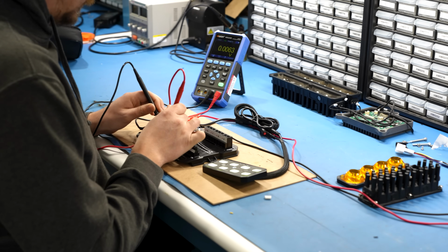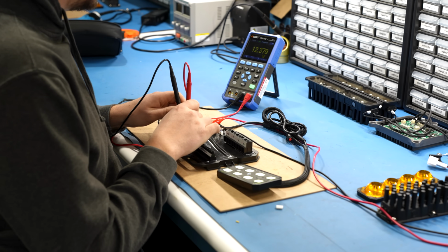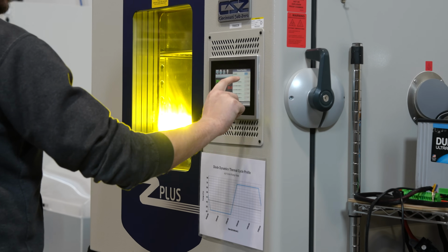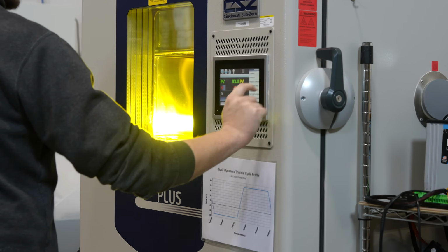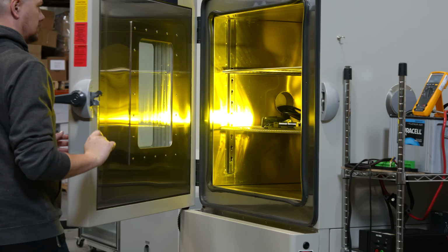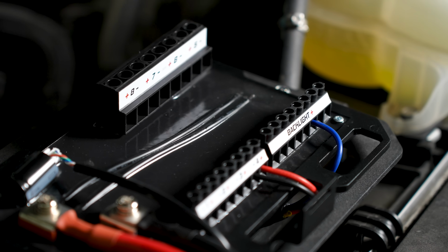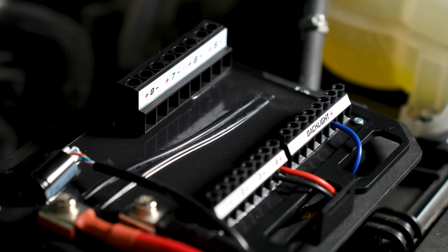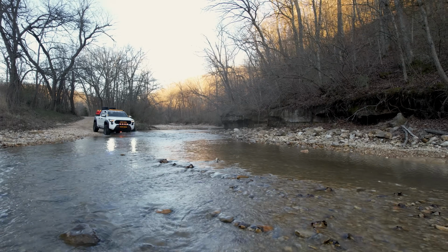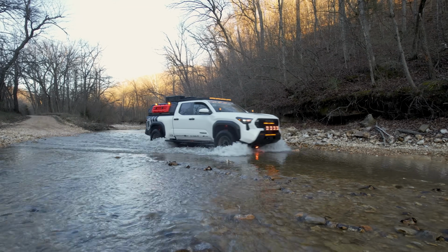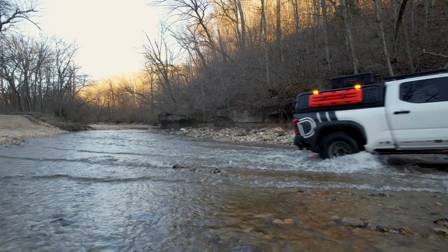We've pushed it to the limits, with rigorous testing to meet SAE durability standards, cycling between -40 Celsius and 85 Celsius, plus an extreme 120 Celsius test for 1 hour at full capacity, to ensure it keeps cranking out amperage even in a hot engine bay. With its IP67 rating, you can rest assured that the D-Switch is ready to handle whatever you experience.